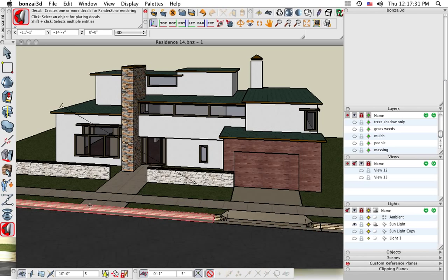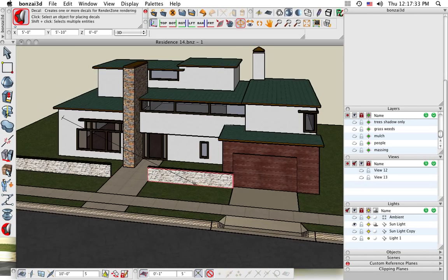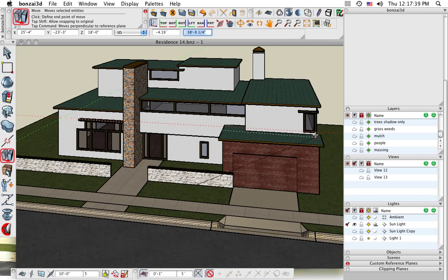All right, now in the shaded work mode, if I were to move that sunlight, let's click on that sun and move it, I don't see any difference in the scene. I don't see any shadows, I don't see any lighting variations or anything. And that's because we're in a shaded work mode, which is a standard mode for creating geometry. What that does is it puts a light on your forehead, so you're always looking at your geometry and the light is shining from your current position, so it fully lights your scene.